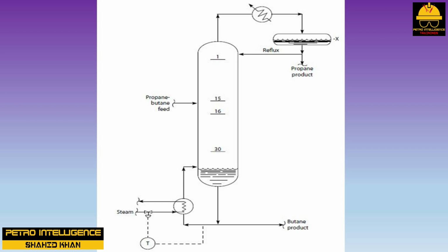1. The tower top temperature drops. 2. The amount of butane in the overhead propane product drops. 3. The tower bottom temperature starts to fall. 4. The reboiler duty increases to restore the tower bottom temperature to its set point. 5. The weight flow of vapor and the vapor velocity through the tray increase. 6. The spray height, or entrainment, between the trays increases. 7. When the spray height from the lower trays impacts the upper trays, the heavier, butane-rich liquid contaminates the lighter liquid on the upper trays with heavier butane.